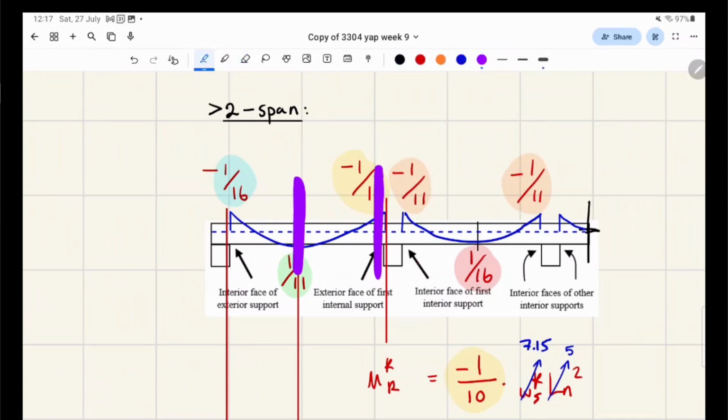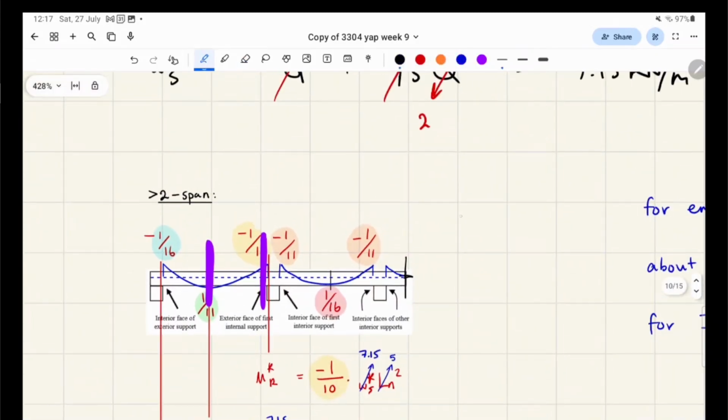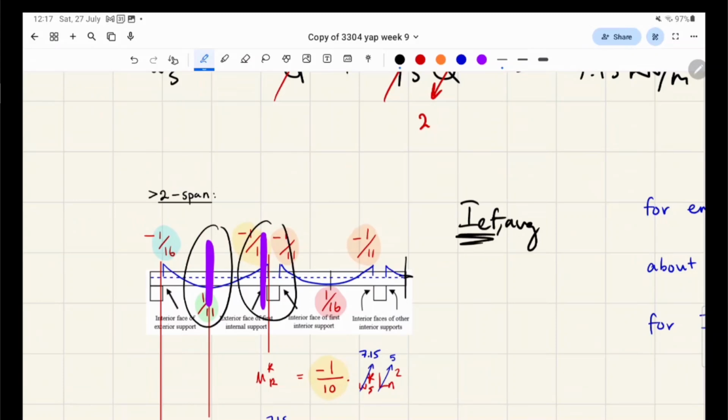Because in the middle there's a lot of deflections, and on the continuous end there's going to be, I shouldn't say deflections. I should say it's because of the M star. That's not a good way to put it. Anyway, this formula for I_ef average takes 50% of what the effective I is here and 50% of what the effective I is there. That's what's required of that formula. So we analyze those 2 cross sections.